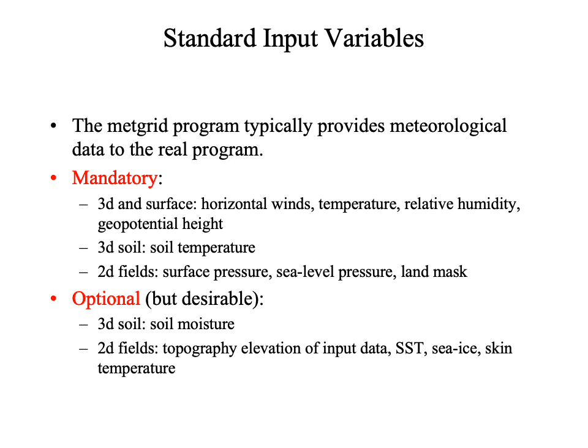These vtables are associated with specific national center data sets that the WRF model understands and knows about. The vtable is able to pull out the necessary information from the GRIB files and provide that information into the METGRID program, and that's moved along into the REAL program for the vertical interpolation and diagnostics.